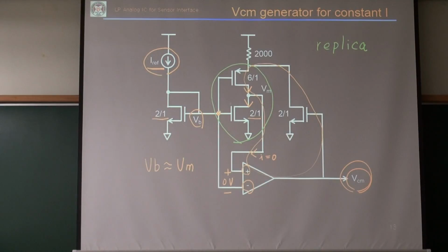Yeah, this is nothing but logic threshold voltage of this inverter, right? Because input and output are equal to each other. Okay. So then this inverter works at the logic threshold voltage, logic threshold point with some VDD prime here. This is a VDD2 maybe.